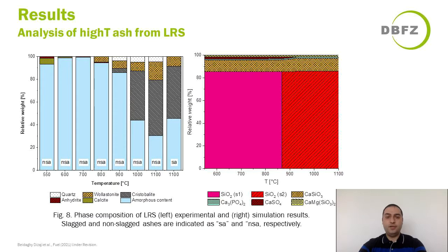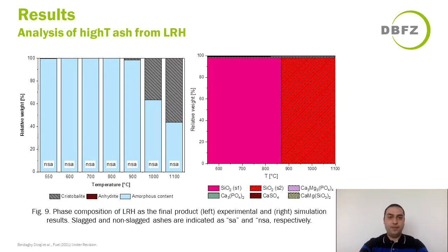And the same information comes for the acid-leached rice straw. And we have calcium silicate as a dominant phase except the silica phase in our leached rice straw sample. But the share of wollastonite decreases by acid leaching compared to the water washing, and the level of the silica purity increases by applying the pretreatment. And the maximum purity for silica comes from the acid-leached rice husk sample, which we detected almost pure silica for all the temperatures. And by controlling the temperature, we can produce pure biogenic silica in the form of non-crystalline material, as an amorphous silica.